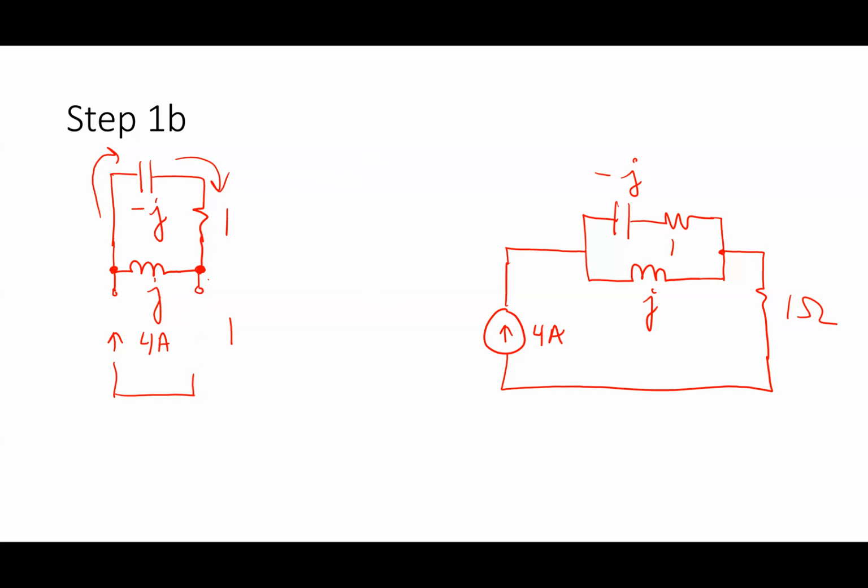When I'm using this equivalent circuit approach, I'm always breaking at a set of terminals and saying, okay, what's equivalent on the other side of those terminals? And then making the replacement of the equivalent impedance. That's the basic approach that we always follow in this approach. Questions about that? All right.